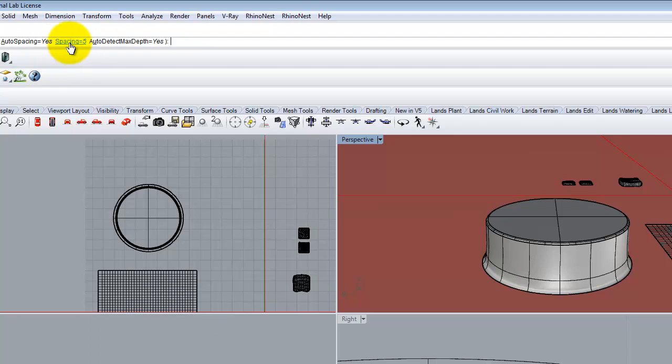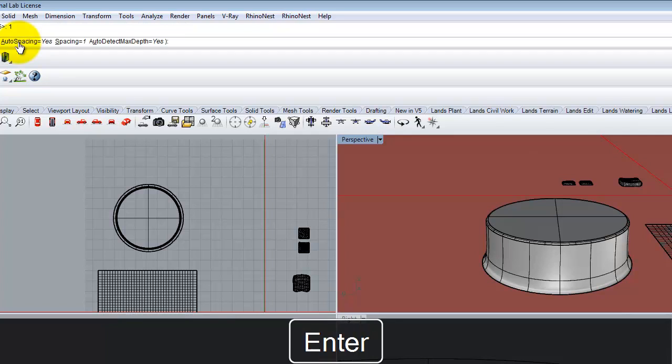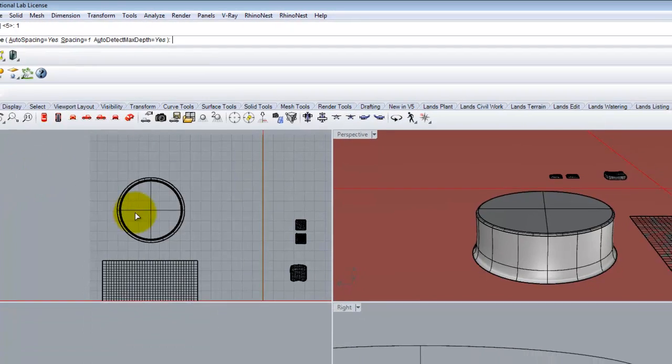The only thing we're concerned about here is the spacing. What it does is it takes a sample of height every 5 inches. So if we imagined a grid of every 5 inches, because the spacing is set to 5, it says, okay, give me a point as I look straight down on the surface, and I'm going to sample from that. And when it goes down, if I move 5 inches over and it goes down, that's my new point. So if I change this to, say, maybe 1 or 2, we'll start at 1, it's going to sample at every 1 inch over the top of the table.